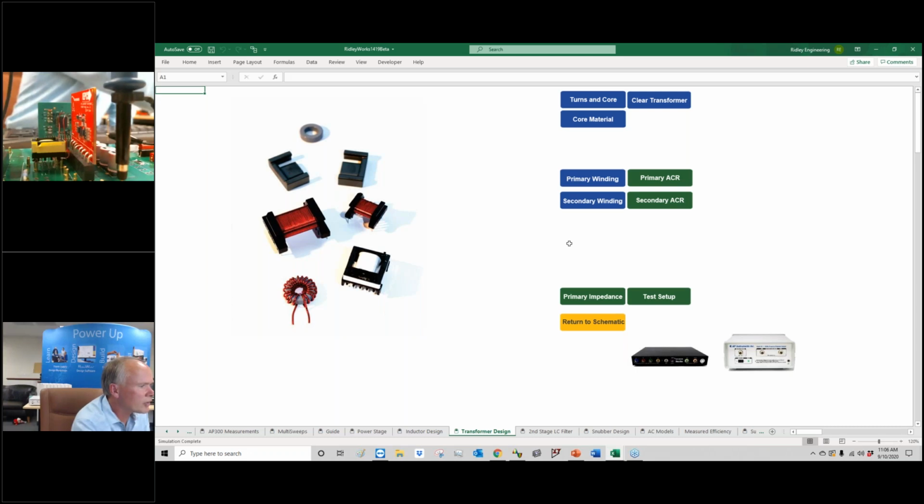Webinar on coreless transformer designs. That would be the transmitter webinar. So if you want to know about coreless transformers, go study transmitters. Okay, if you're doing a power supply, not a good idea. Many have tried it. Fin6 was the famous one. We're going to do a coreless transformer at 50 megahertz, right? So they build themselves a transmitter at 50 megahertz, and then they put the core in to make it a non-coreless design.